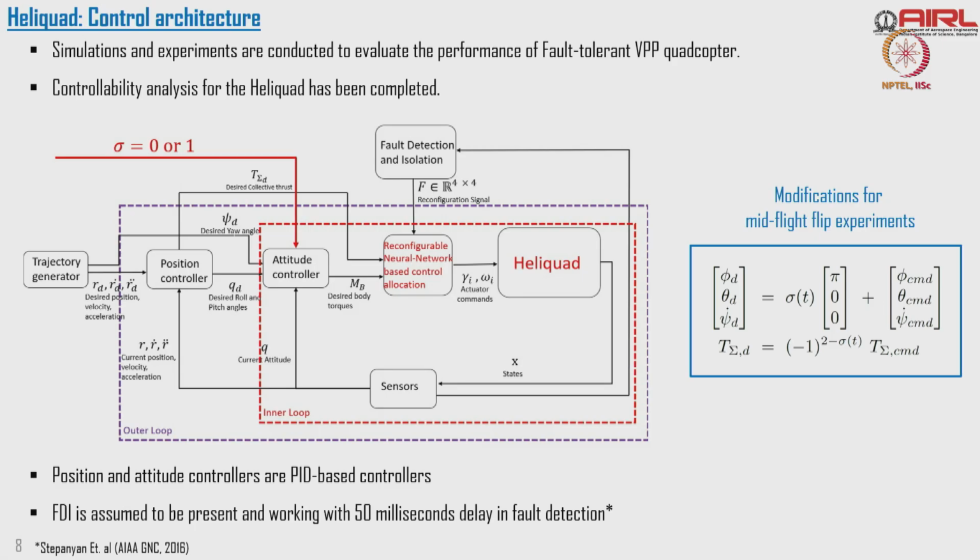But you see here I am using a variable pitch aircraft, and I want to handle the fault tolerance also. Fault needs to be detected. Fault detection and isolation is needed because you need to know which propeller has failed. Based on that you have to deactivate the other motor. What I mean is the other motor has to change to a condition where it produces zero thrust but positive torque. That torque can counteract the torque produced by the other two motors. So I need to know. So the fault detection and isolation system comes into the picture.